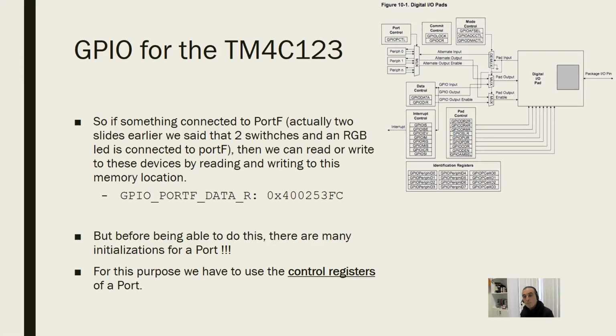This is called port initialization. And we use control registers to do a port initialization. And we are going to do it in code. Which registers, what is their memory location, what happens when I change a bit on those registers? Everything is written in the datasheet.